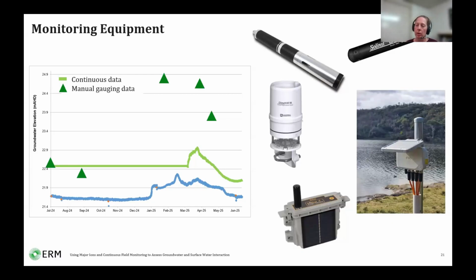Being used more commonly in the industry is telemetry, which provides data directly back to the office via satellite link. I haven't used telemetry a heap myself. I know that the pros include accessibility at remote or inaccessible sites, and real-time data, so not just when you happen to go back and pick up your data logger and download the data, but you can also set them to trigger warnings at certain levels. And I believe they can be integrated with new or existing sensors.